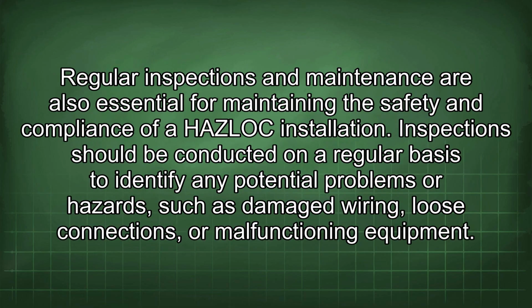Regular inspections and maintenance are also essential for maintaining the safety and compliance of a HAZLOC installation. Inspections should be conducted on a regular basis to identify any potential problems or hazards, such as damaged wiring, loose connections, or malfunctioning equipment.